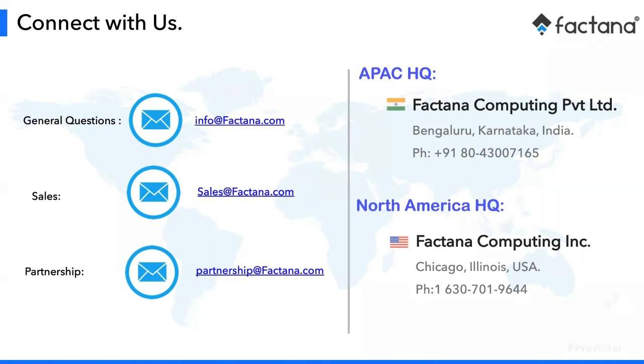The next question is, can SFactrix also show metrics like TEEP in addition to OEE? TEEP, yes. Actually, right now we are showing TEEP as an overall. If you look at the loss matrix, the production losses are all calculated based on TEEP only. TEEP is your overall asset time, the overall time, and then how much OEE time there is. So if you go to our loss-based metrics, they are all calculated based on TEEP. It's not explicitly saying TEEP, but it is basically breaking down the TEEP into 4 pieces and showing you the losses, the total availability, and how much you have utilized. Yeah, it is there, but we are working on some more TEEP features.